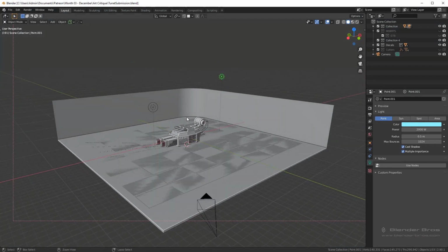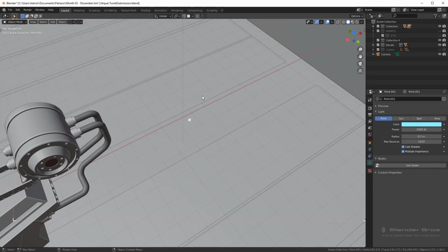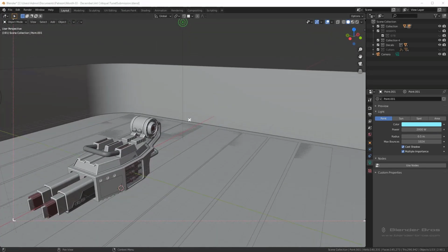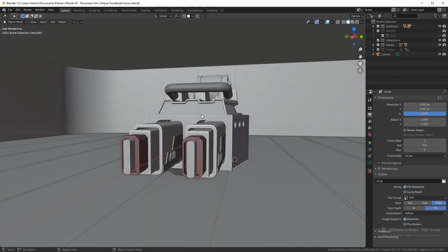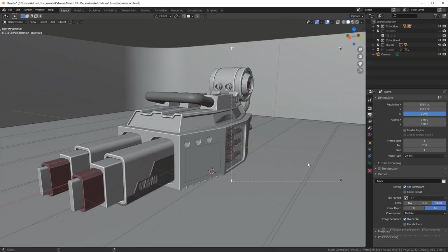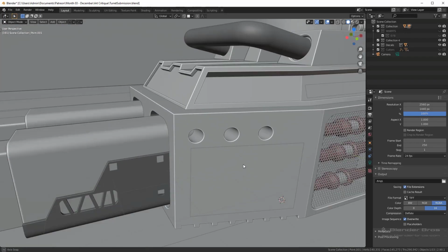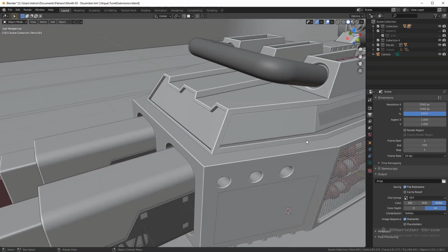Looks like you have this border. Let me press Control Alt... What was it? Control Alt B. There we go. Control B for the render region, Control Alt B for getting rid of it. Okay, so let's go ahead and take a look at this model here.